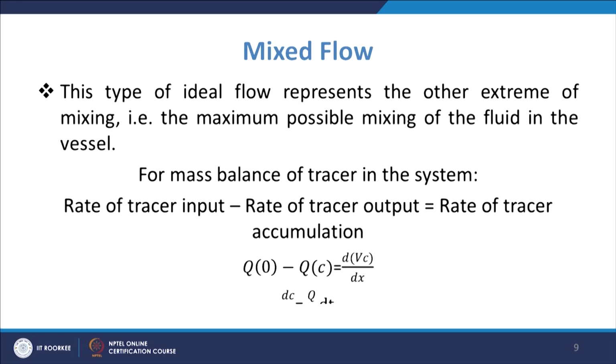Now, next will be your mixed flow. The mixed flow is the type of ideal flow that represents the other extreme of mixing, that is, the maximum possible mixing of the fluid inside the vessel. In plug flow the fluid maintains its identity, whereas in mixed flow it is assumed that once the tracer has gone inside the vessel, it has completely mixed inside.